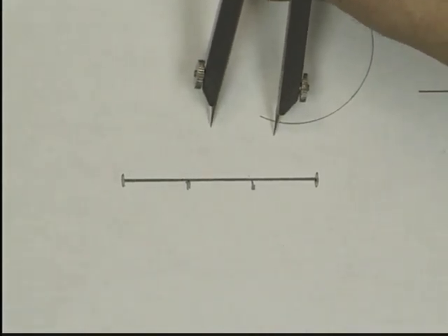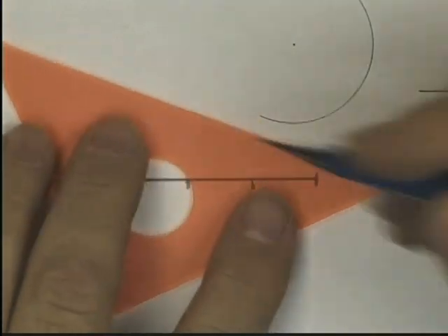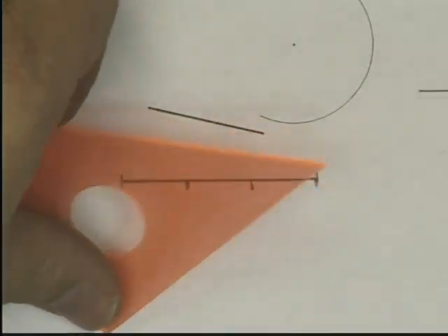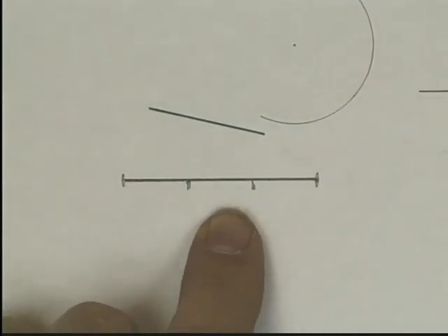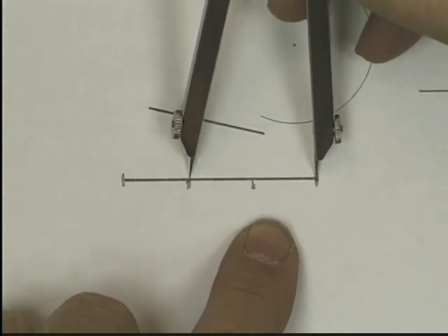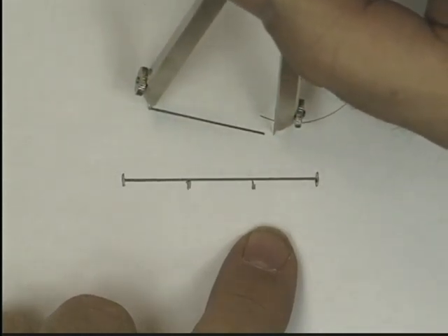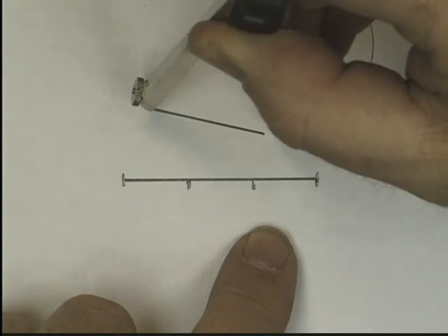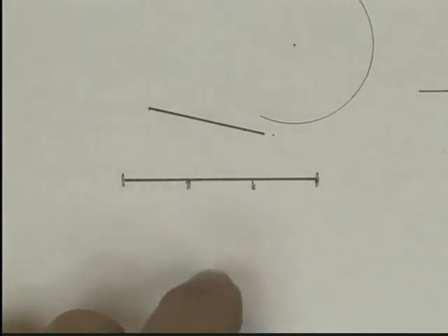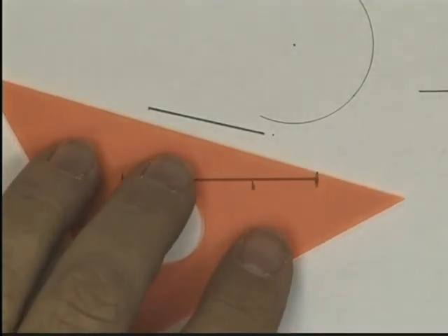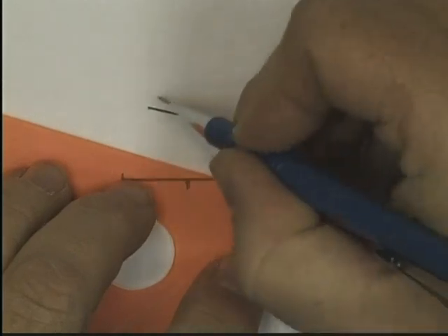Suppose I had some other line on my drawing. Let me just put one in here. And I needed a distance on this line that was exactly 2/3 of the distance on the original line. So let me set this here at the second mark, 2/3, and now I can transfer this distance over to this other line. Now you're not going to be able to see this on the video, but I'm giving a little bit of pressure, and I made a little tiny pinprick hole in the paper. And that little pinprick hole marks the exact 2/3 distance that I wanted to transfer, and now I can just extend this line to that point. I'm even going to make a point there to show me that that's where it was.